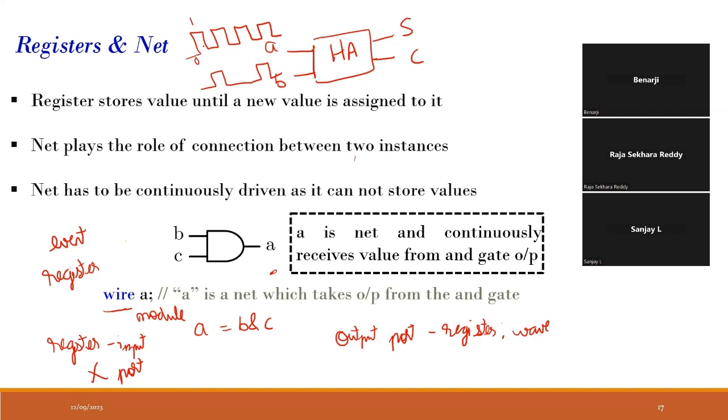It is just input coming in. But for a register, only based on some particular event do we assign it some particular value, and when this is happening, we don't know. That is why we don't use a register data type for the input.